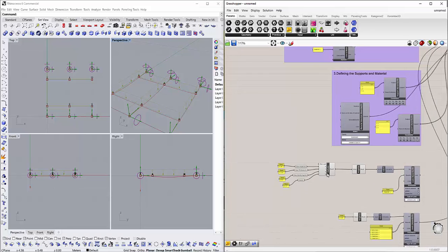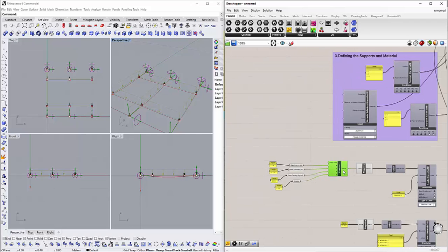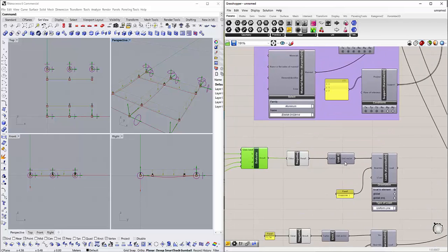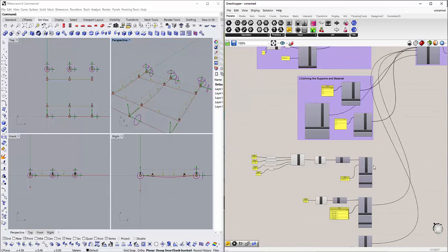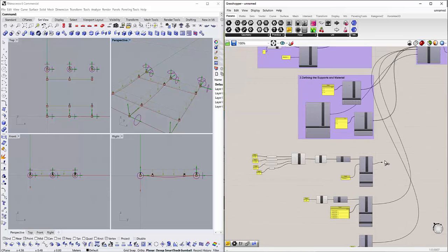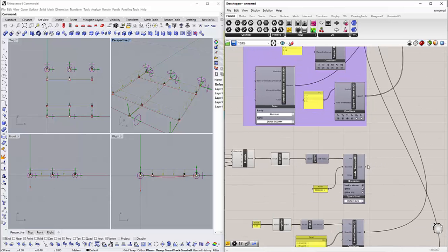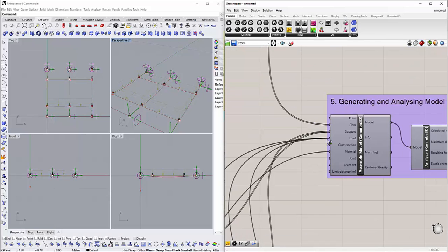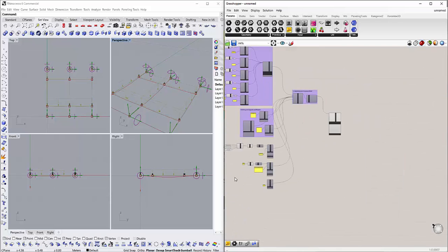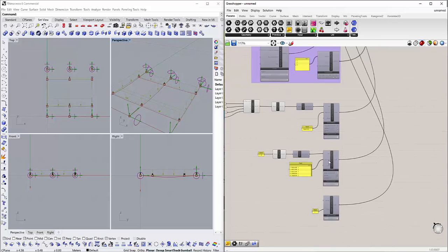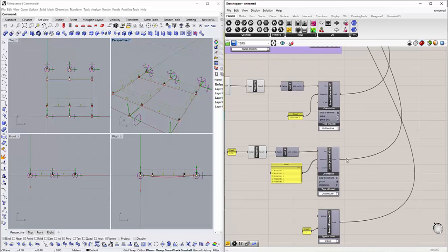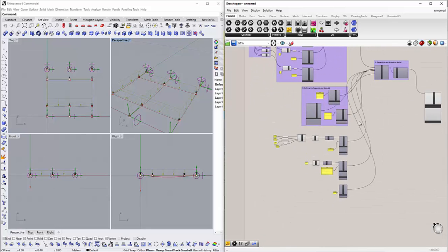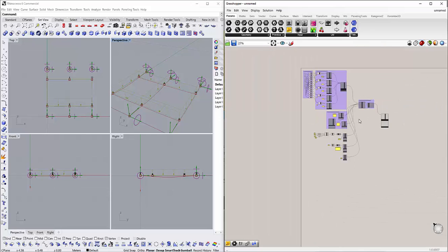So now this load is created, that is the glass load on the transom in the y-axis, and I'll put this load, shift to this load. So all the three loads are added now. You need to press shift and keep on adding this load so that it doesn't disconnect at once.